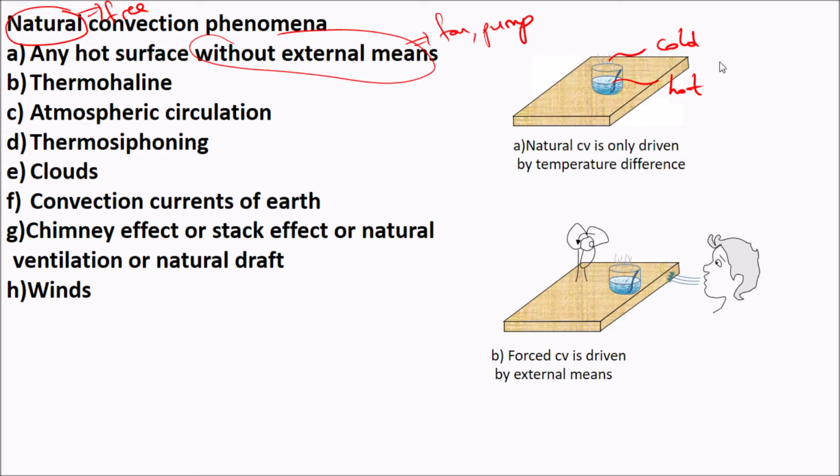If it is hot, it has low density. If it is cold, it has high density. The low density fluid is light, and the high density fluid is heavy. Since it is light, it will rise. And since the fluid rises, you will have heat transfer. You shouldn't mix the fluid flow with the heat flow. Here, these are the fluid flow. But as the fluid rises, it carries heat. Therefore, this is free convection.